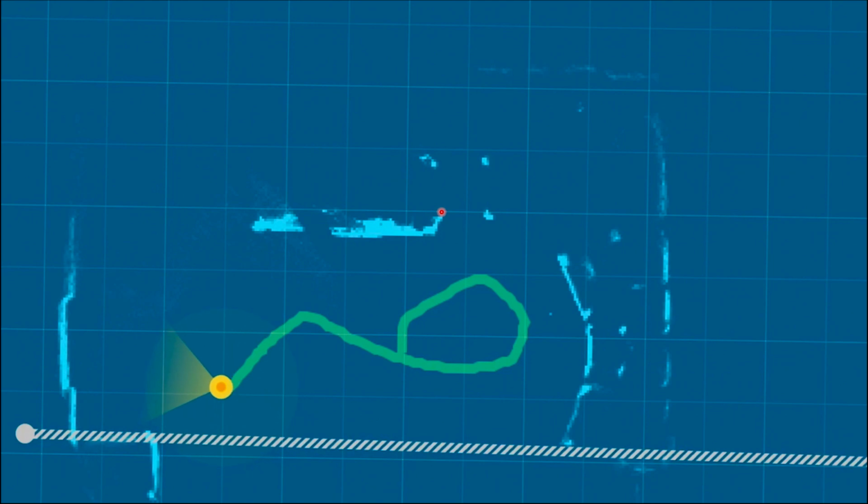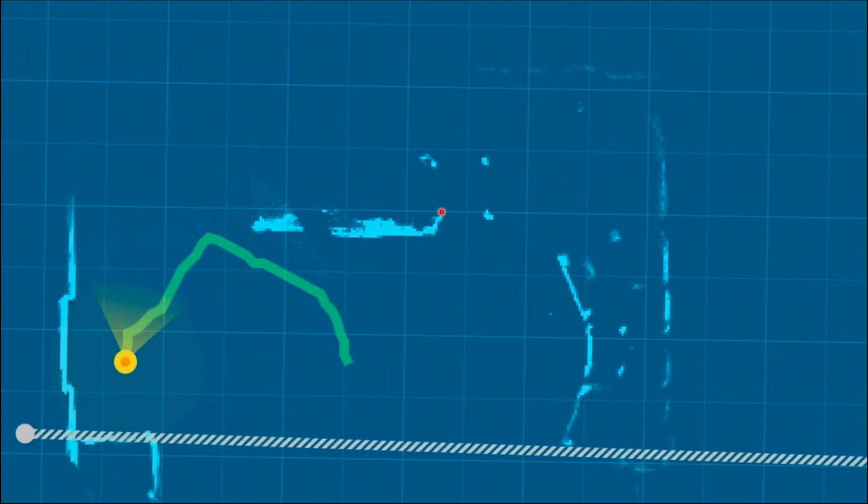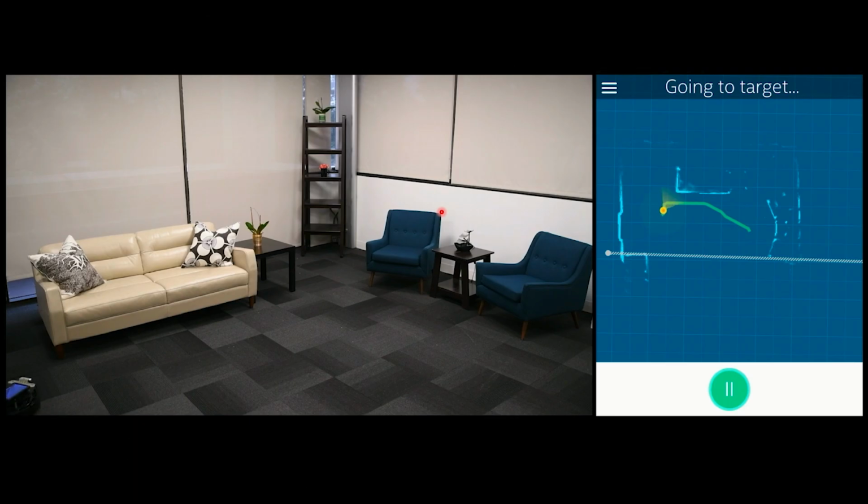So here the robot goes off, explores the space, can be a living room, home environment. It's building a map using, on the one hand, the depth data, the point cloud transformed into a common reference frame, and accumulates it over time to create this map. You see here, for example, the couch, the two couch chairs, the table, you see the two legs. It's going around the couch.